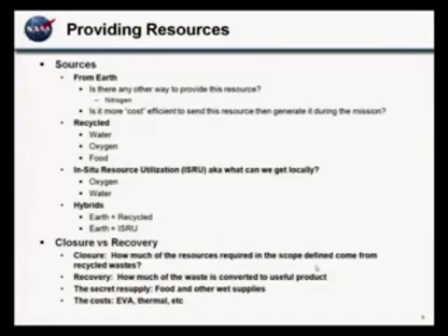But that's water now that you're taking out of the life support system that you don't get back as waste that you can recycle. So that can happen directly in the suits. It can happen with another vehicle, like providing that same thing for a rover or something. It can happen in your vehicle. When we've looked at analysis of the Orion vehicle circling the moon, when you're on the hot side of the moon, your environment is so extreme that you can't use a radiator successfully to reject all of the heat from the vehicle.